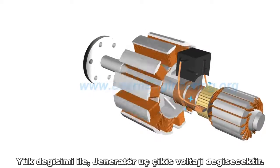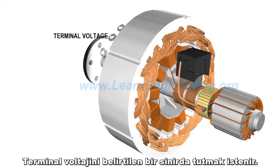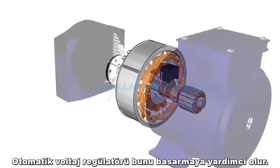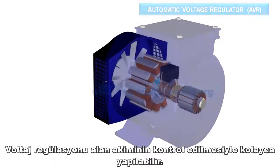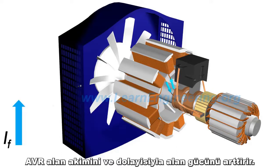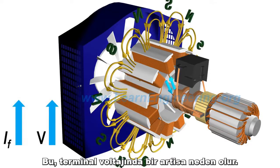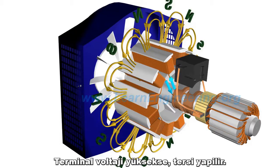With variation of load, the generator terminal output voltage will vary. It is desired to keep the terminal voltage within a specified limit. An automatic voltage regulator helps in achieving this. Voltage regulation can be easily achieved by controlling the field current. If terminal voltage is below the desired limit, the AVR increases the field current, and thus the field strength. This will result in an increase in terminal voltage. If terminal voltage is high, the reverse is done.